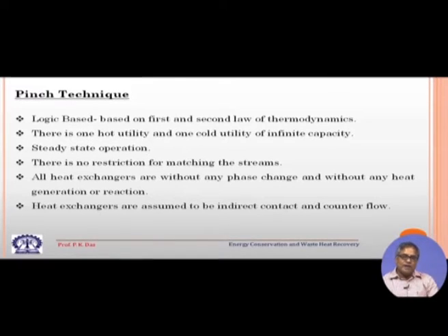First law and second law of thermodynamics we follow for the pinch analysis in a very intelligent manner, and we never violate the first law or second law of thermodynamics. Obviously, if we violate these basic laws of nature, then the design will not be fruitful. So, by abiding these laws, we try to get the optimum kind of arrangement of the streams and heat integration.